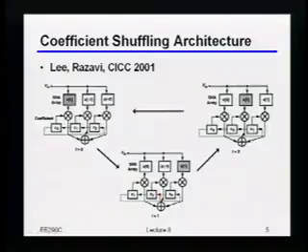Then in the next time phase, and the time phases here are obviously controlled by the clocks, and I'll draw a picture of that in 1 second just to make sure it's clear, I can still take that same sample that I had from one time phase ago, but since I've advanced by one time phase, its meaning has shifted, right? So if before it was the cursor, then now it would actually be the first post cursor, right? Because I'm one time sample later. So I could just take that same sample value, and on this one it used to be x0, now instead of feeding it to c0, I feed it to c1, right? Because now it's supposed to be the first post cursor.